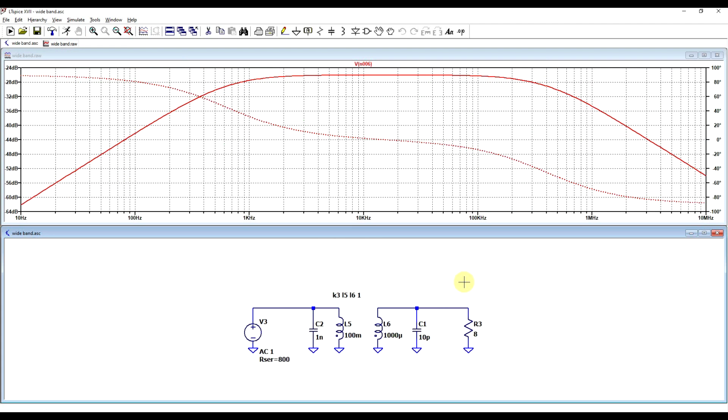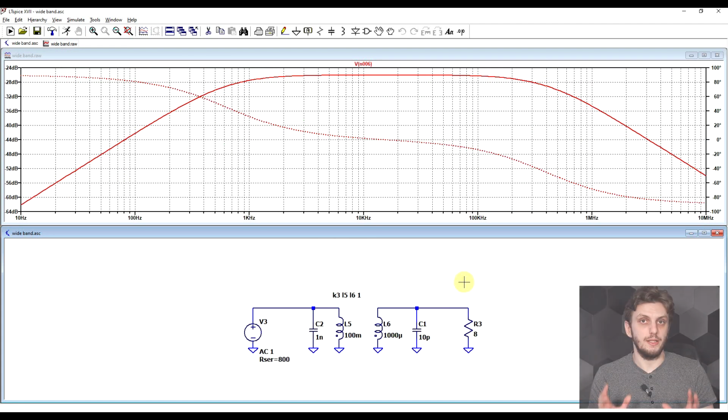We're getting a high pass effect at low frequencies because of the inductance, and we're getting a low pass effect at high frequencies because of the parallel capacitance. The key in getting a wide bandwidth is therefore very large inductors, but also very small parallel capacitance. To a certain extent, capacitance is linked to the number of turns. More turns means more capacitance, so to get both low capacitance obtained with few turns, but at the same time a large inductance, you will most definitely need a magnetic core providing magnetic permeability.